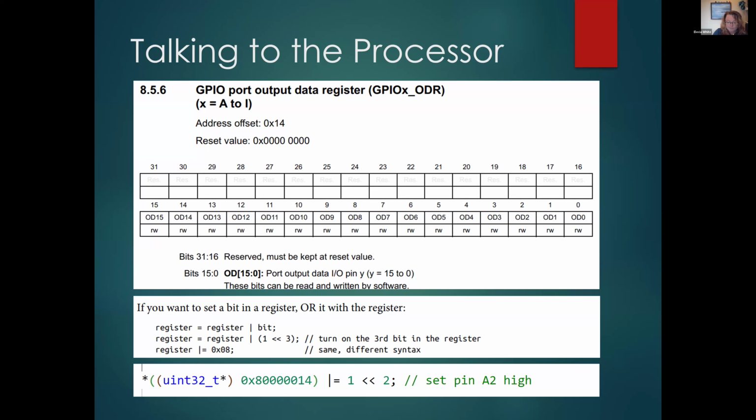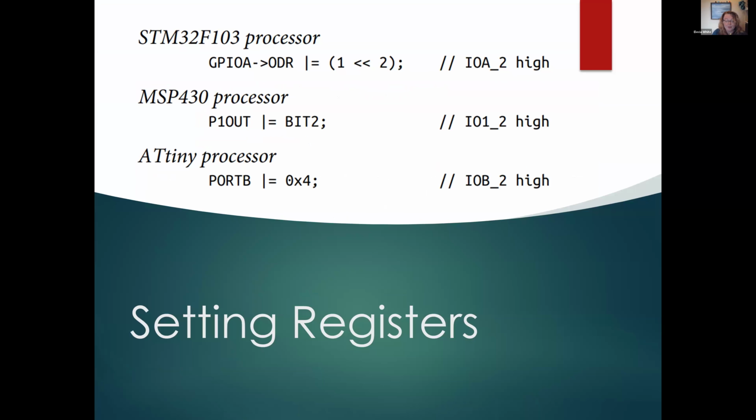However, don't do that. That code is just as hideously ugly to us C programmers as it is to anyone else. The processor vendor almost always provides a memory map of the chip so that you can use these registers as global variables or as part of a structure. These are part of the hardware abstraction layer. Usually it's more than simply a header. Sometimes it's a whole set of libraries. Note that the register names are different for each processor, but the effect of the code is the same. In each line, it is setting the second bit in the byte or word.